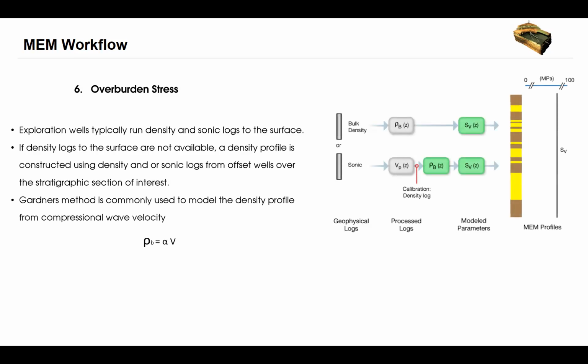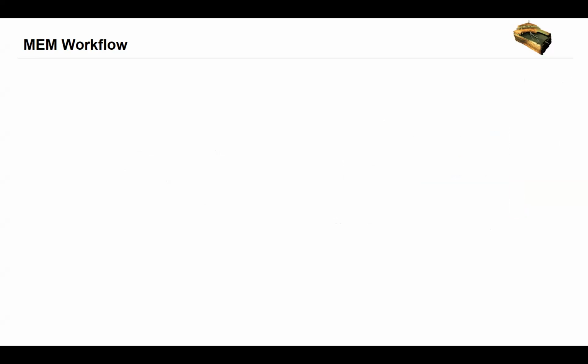These are the steps. In general, there is no direct calibration for vertical stress. This is a very big issue for geomechanical engineers, but occasionally hydraulic fracturing stress measurements measure the vertical stress, but this is a very rare exception. It happens when the induced fracture propagates in the horizontal plane of fracture. The primary opportunity to improve the overburden stress model is to measure bulk density over sections where it has been modeled, if it is possible. If it is not possible, no need.